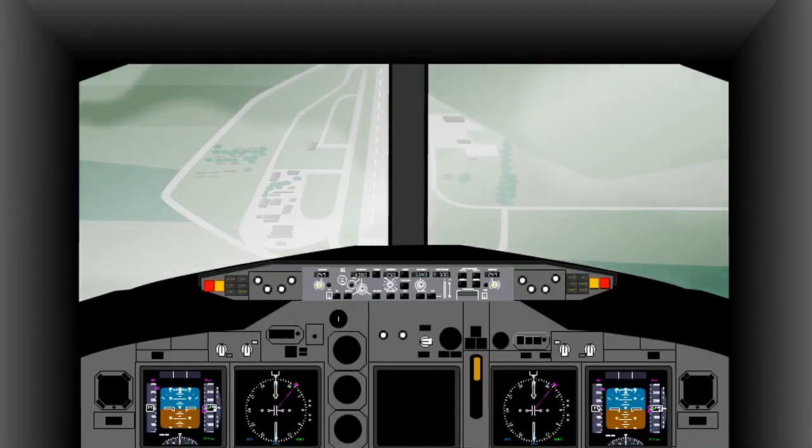The minimum visibility to undertake a visual approach is RVR 800 meters. Of course, if already operating in at least 1,500 meters, the minimum for a Category A aeroplane, this minimum should not present a problem unless operating in conditions of shallow fog or low drifting sand or snow. This concludes our investigation of aerodrome operating minima.